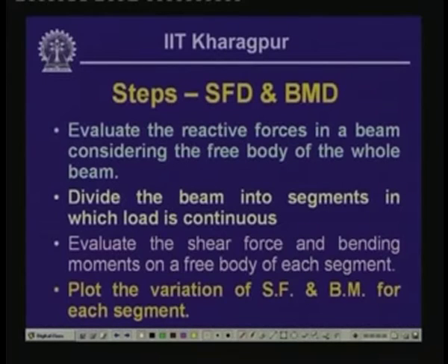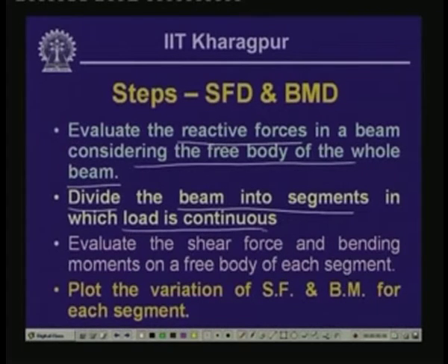The first thing, as you have noticed, is that we draw the free body diagram of the whole beam, and thereby we represent the supports with the reactive forces, and we evaluate those reactive forces based on the equations of equilibrium. So, the first step is to evaluate the reactive forces considering the free body of the whole beam. Then you will have to divide the beam into segments in which the load is continuous.